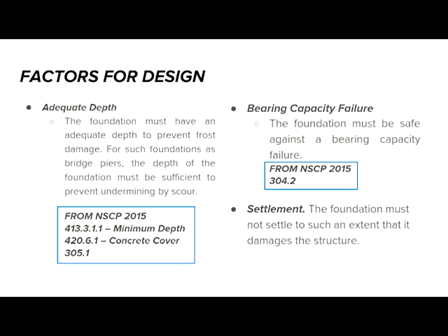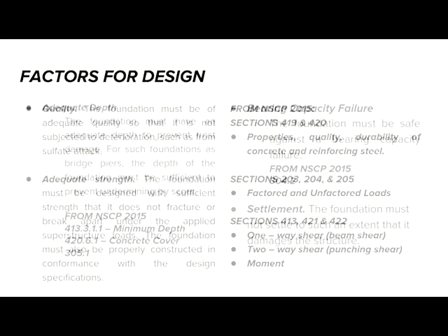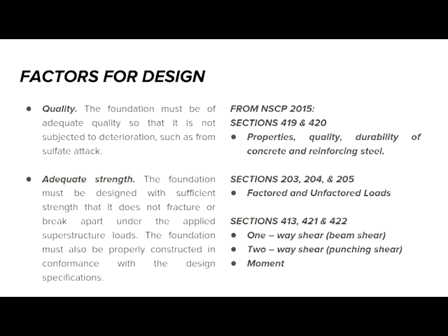Next, settlement. The foundation must not settle to such an extent that it damages the structure. So this is what I already said before. Next, quality. We need to make sure also that our foundation, regardless of what it is made of, must be of adequate quality, that it is not subjected to deterioration such as sulfate attack for concrete or rust for steel.